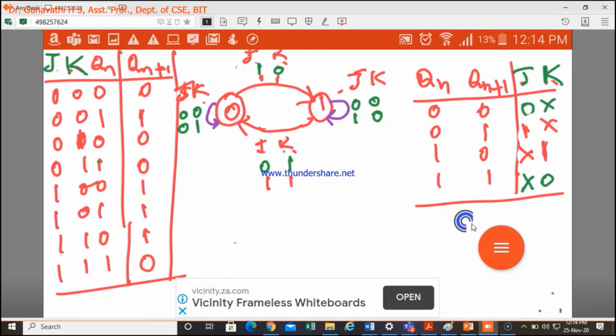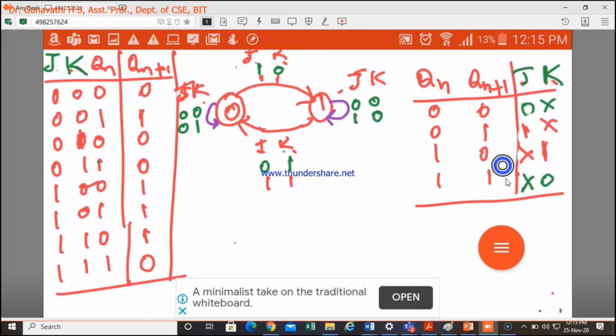Yeah. So you have to remember the excitation table of all the flip-flops. Where these flip-flops can be used in the counter design, and in the CPLD reports you generate, right? When you simulate in the Xilinx, this toggle flip-flop is also used internally in order to build that. So with respect to the lab experiments, we'll be using this JK flip-flop to realize the sequential counters.